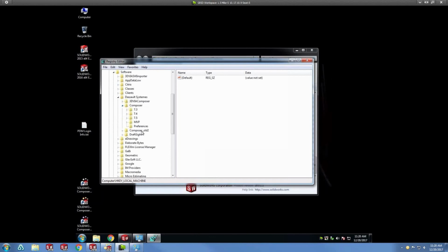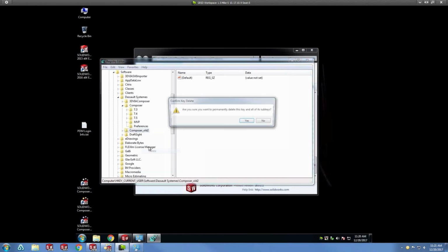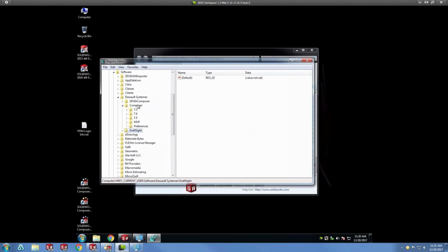Now, as we see here, I did leave an old file. We'll go ahead and clean that up here. Again, please don't delete any files unless you are 100% sure of their use. Now we have Composer listed here. I want to ensure that Composer is closed. I can check that here. I don't see that on my toolbar. What we would want to do is right-click this file and rename this. Generally, we will add old to the end, as it is a fairly easy way to see.